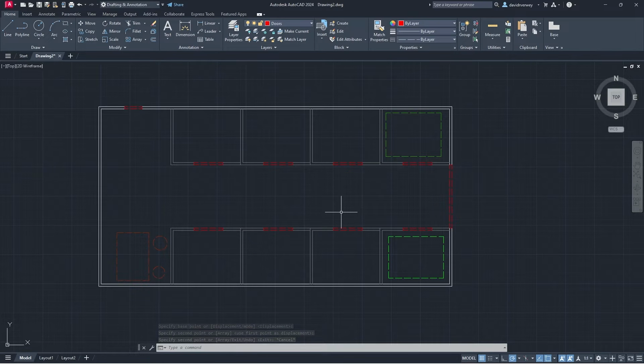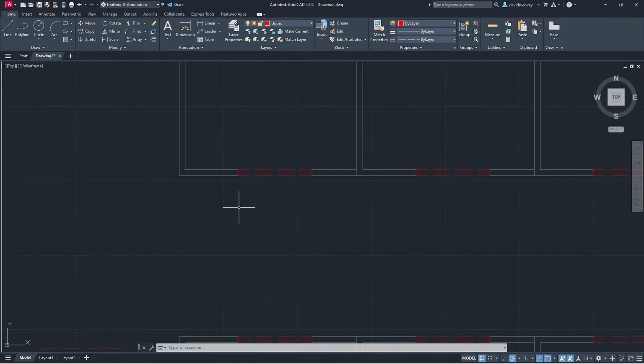We don't have our windows yet, but that's okay. What we're going to do is make our door swing. Inside of barns, you usually swing the door out, and they usually go quite a bit. So I'm going to take an arc and create one. I select the start point, specify the second point, and then, sorry, I completely screwed this up.